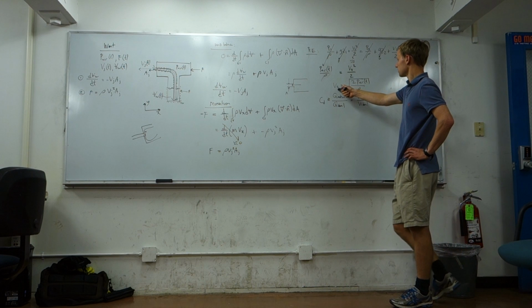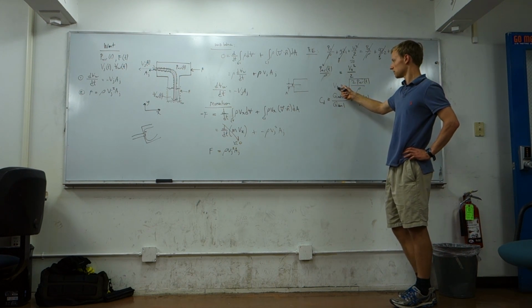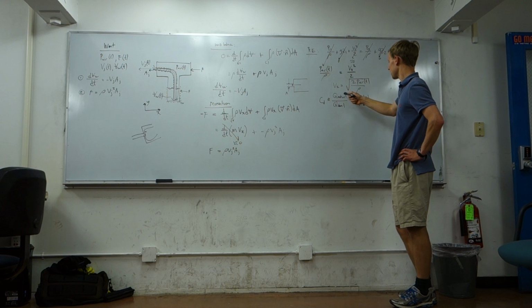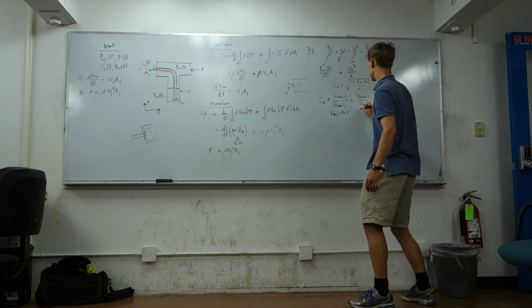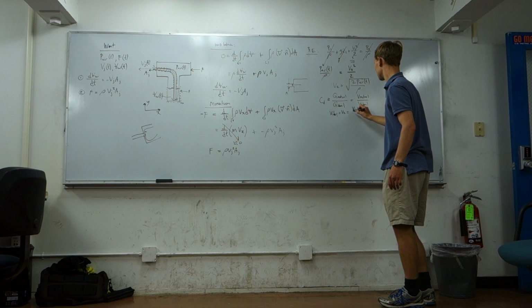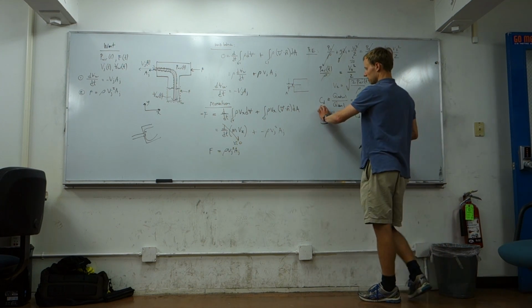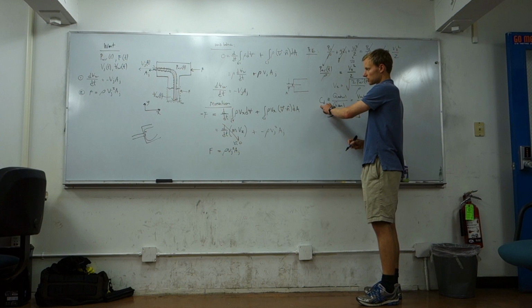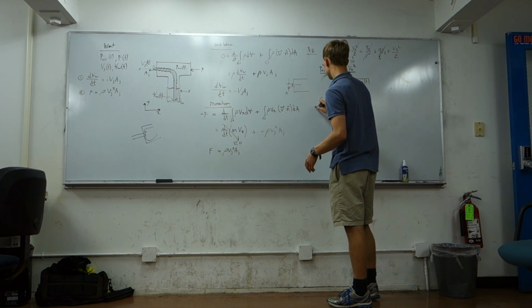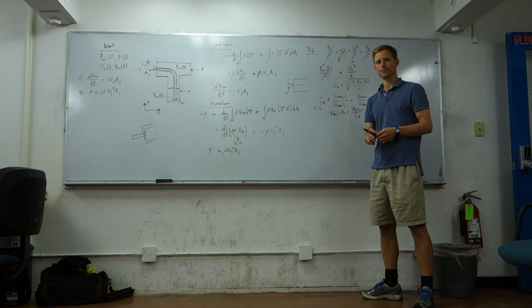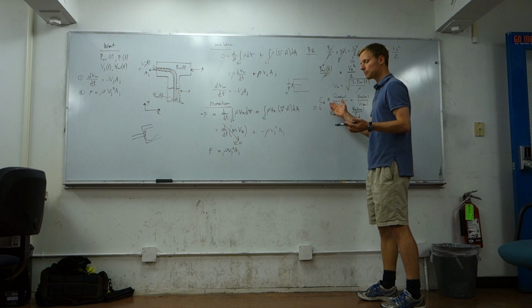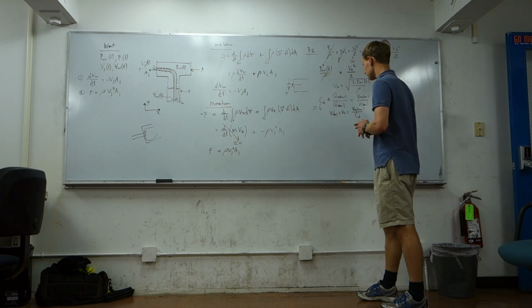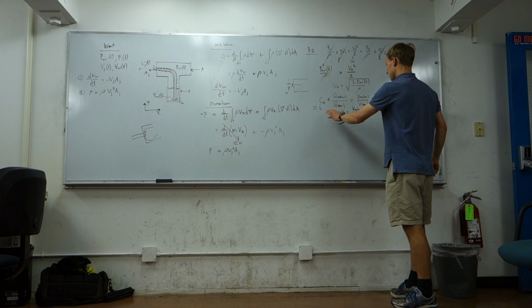And if we look at our Bernoulli's equation, we just use V2, which is our ideal velocity, since we assume it's inviscid. So we're going to try to plug in for ideal velocity there. So V ideal equals V2 equals V actual over C sub D. Now C sub D is an empirically measured quantity. For nozzles of this type, for this sharp contraction, it's about equal to 0.6. For better, more gentle constrictions, it's more like 0.9. And we actually could do an experiment in the lab in which you would measure CD. But we'll use 0.6 for this experiment.